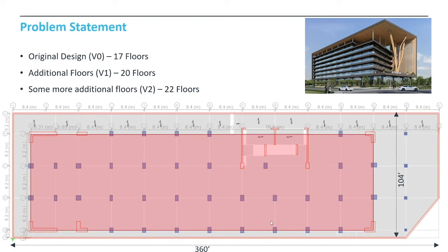I have one question, Ashish. Do you do any treatment to assure the adhesion between the old concrete and the new concrete? We just asked them to chip off the existing column faces or shear wall faces up to a half inch, and then pour the new concrete. But there was no treatment with chemical adhesive or any other solution. It relied on the friction between the old concrete and new concrete.